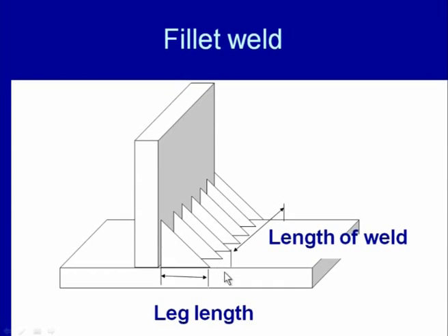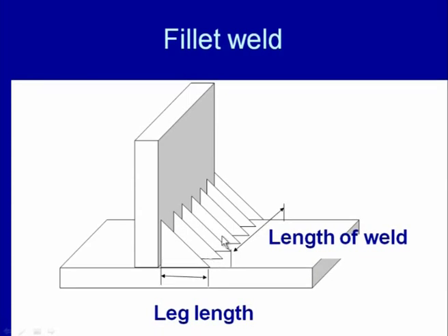Since the minimum fillet weld size is fixed for a given plate thickness, that is to be deposited, which will give us the leg length, and from this we can identify the throat thickness using the suitable equation. This throat thickness will be used in combination with the external load for which the weld is to be designed to identify the length of the weld to be obtained. So, basically we use the external load for which the weld joint is to be designed, then allowable stresses and the throat thickness of the weld to determine the length of the weld.